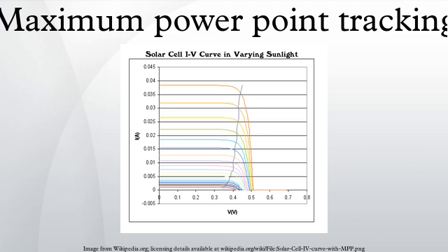A photovoltaic cell, for the majority of its useful curve, acts as a constant current source. However, at a photovoltaic cell's MPP region, its curve has an approximately inverse exponential relationship between current and voltage. From basic circuit theory, the power delivered from or to a device is optimized where the derivative dI/dV of the IV curve is equal and opposite to the I/V ratio. This is known as the maximum power point and corresponds to the knee of the curve.